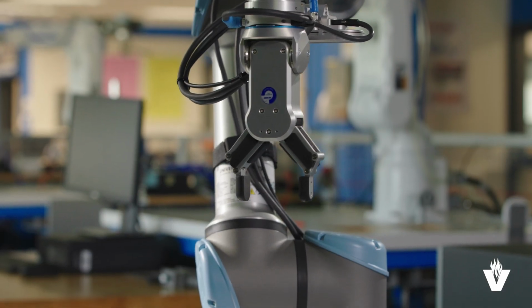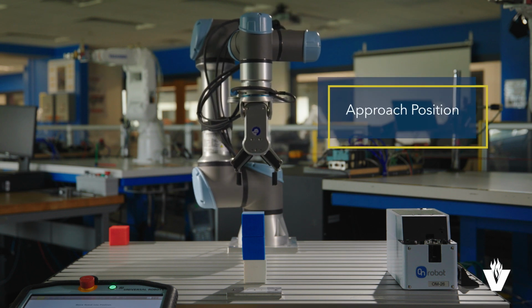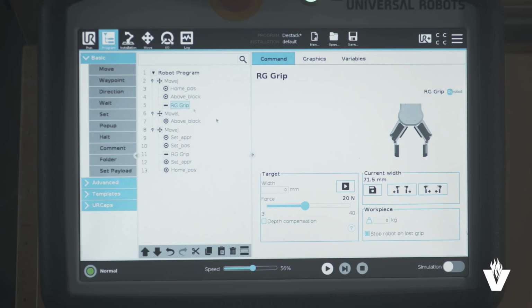First, we position the robot above the blocks. This is called the approach position. This is the position the robot will move from while using the direction node. Next, we need to close the gripper at this point.